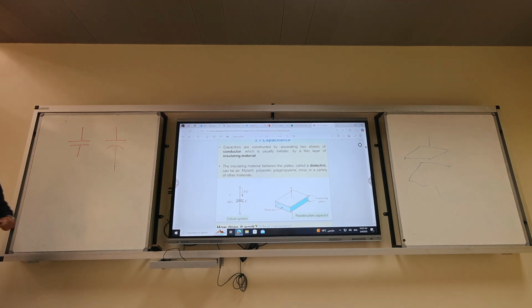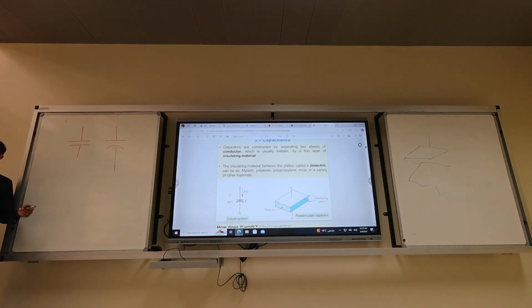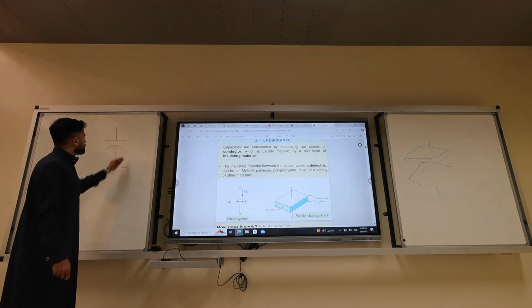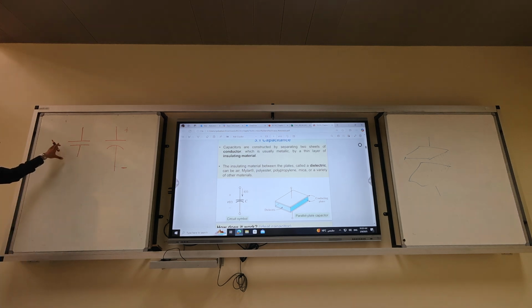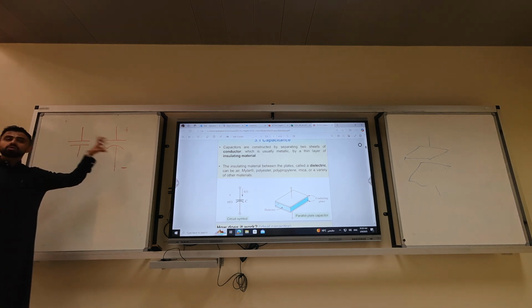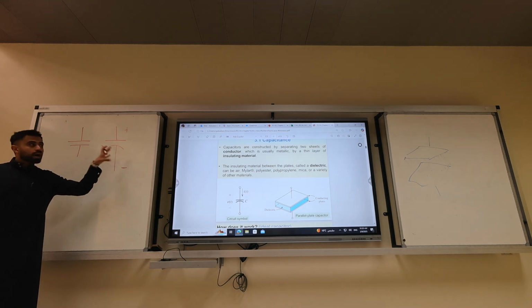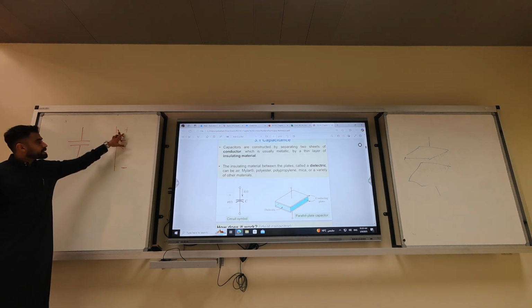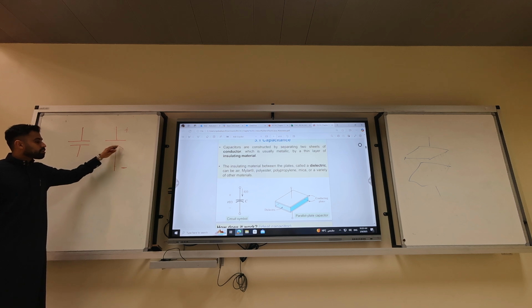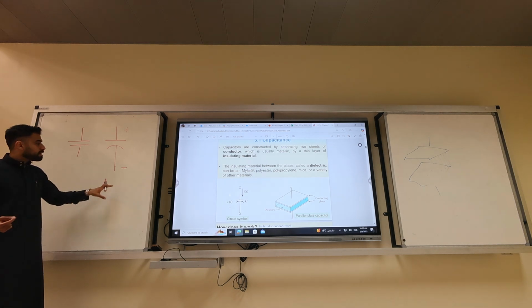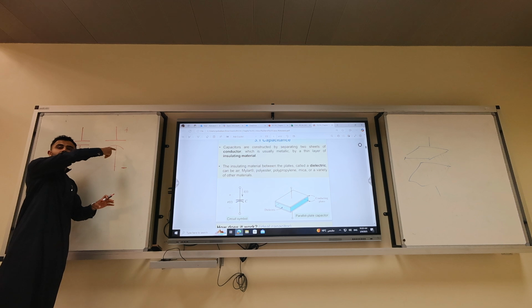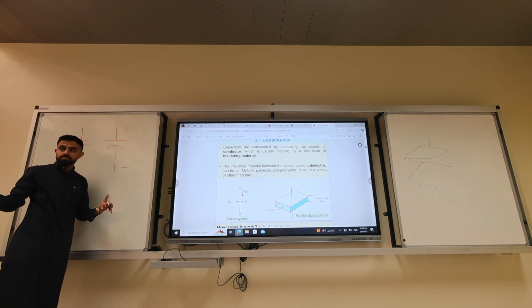What is the difference? If you notice here, the negative and the positive, the negative is toward the arc. In reality, there are capacitors that are unidirectional. It means you have to connect it in the lab, plus and minus, according to the arrow drawn. In the actual capacitor, they draw a line telling you which part is the negative. If you reverse polarity and connect it to the higher voltage, you will burn it.